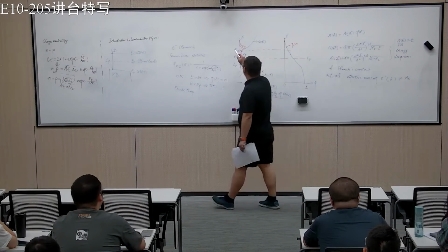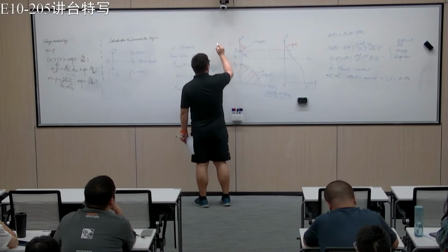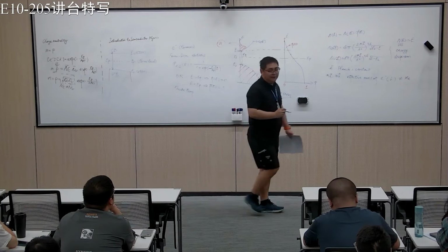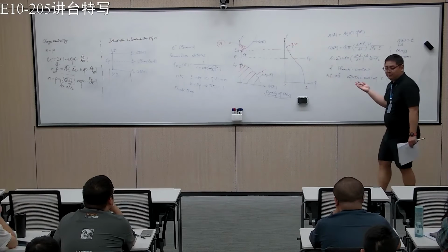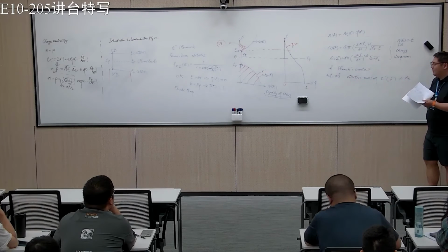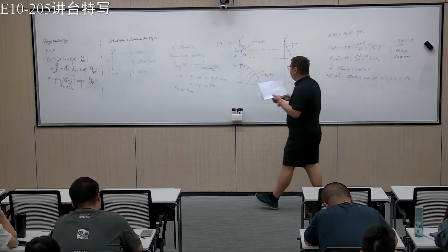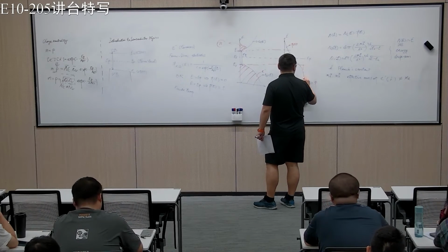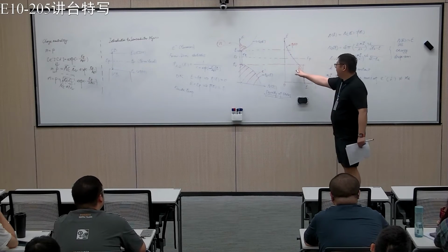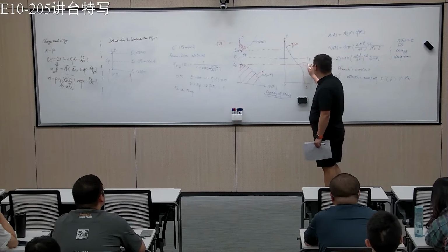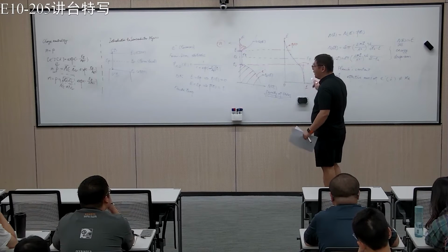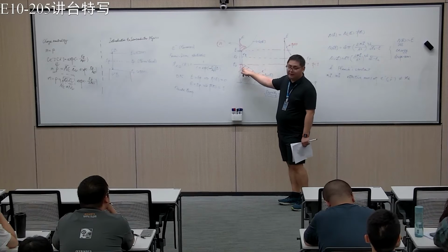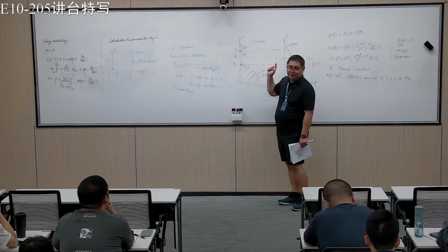And basically, if you sum it, this is the total n. So this is the number of electrons you have in the system, in the conduction band. Again, if you draw a line here, you will see that F here is not 1. F here is less than 1, which means that if you have a state here, it won't be fully occupied, right?